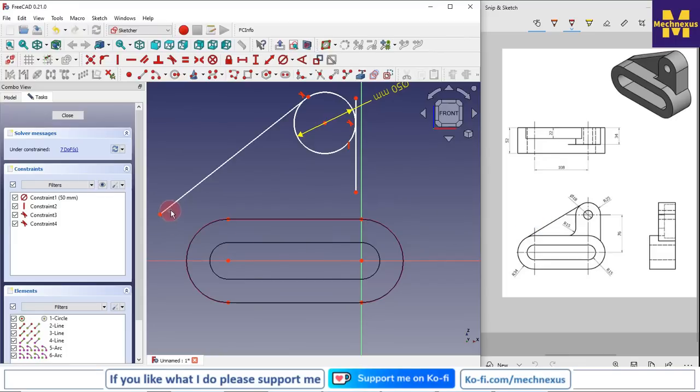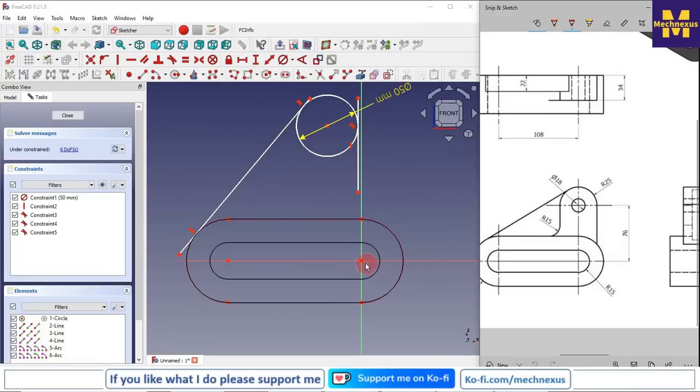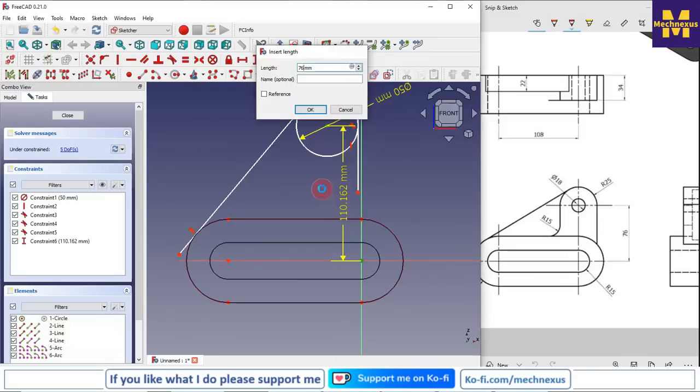And this line will be also tangent with this, so make it tangent. And now we will give the dimension. So this is the 76, so I will select these 2 points and give the dimension of 76.